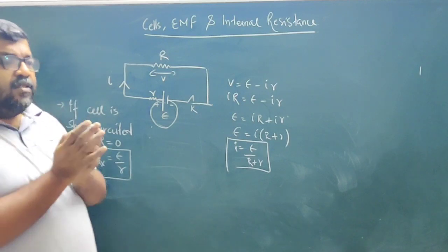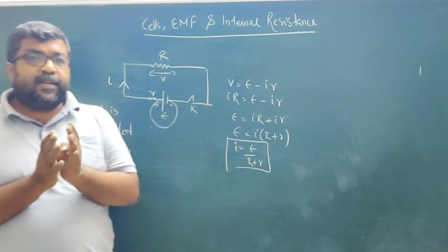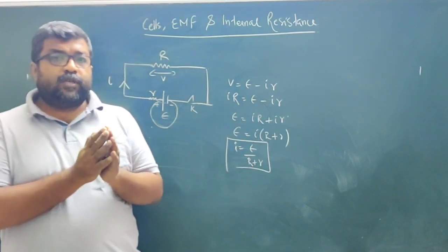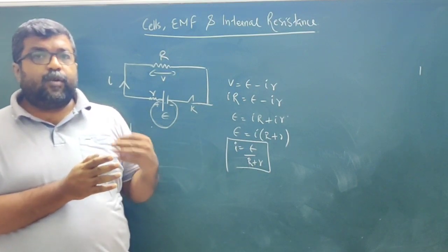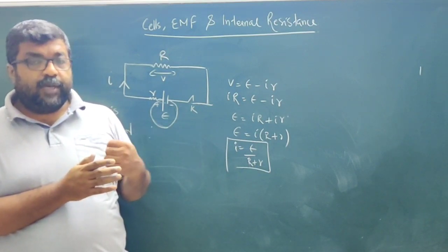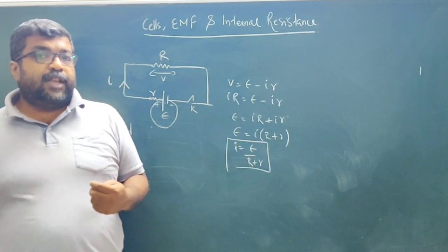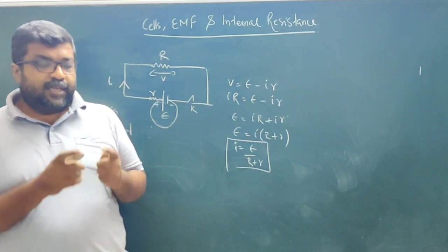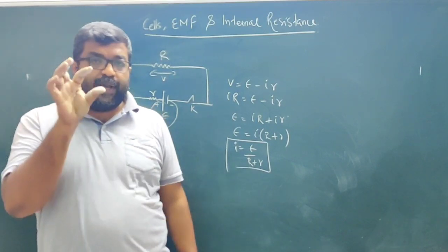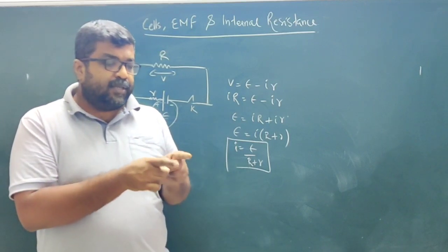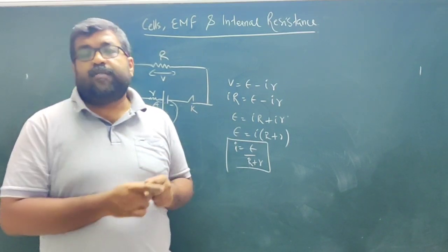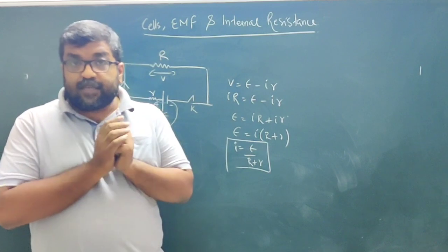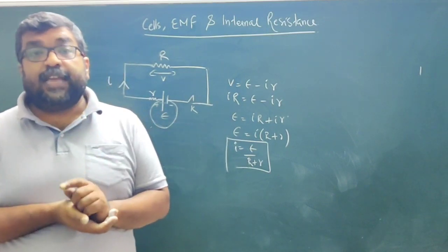This is the reason you might have seen that when your household inverter battery goes down, the electrician comes and uses a short wire to make contact between the positive and the negative terminal of the cell. If there is a spark, that means the cell is alive.